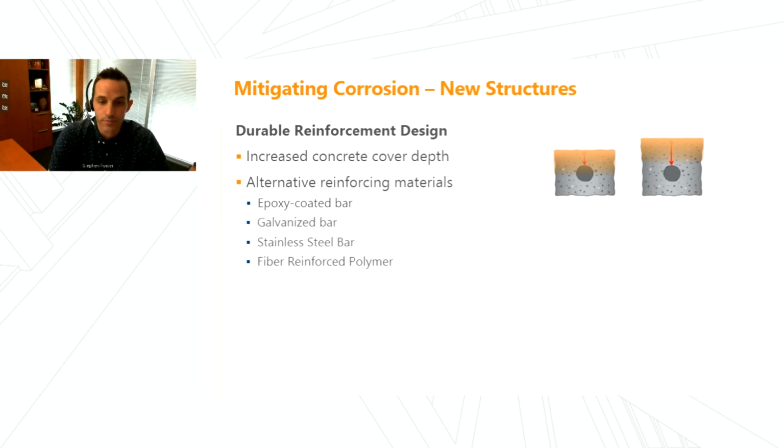Now, the caution there is, depending on the structure type and the type of cracking, if you're going to lower that reinforcing steel or make it deeper into the structure, that could be detrimental to the crack widths. Ideally, having the bar closer to the surface of the concrete will help tighten up those cracks. So again, it's an optimization game where you're wanting to optimize cover depth with shrinkage performance and not getting too much cracking, to where you don't want to put the bar so deep that they're not helping restrain the crack widths near the surface.